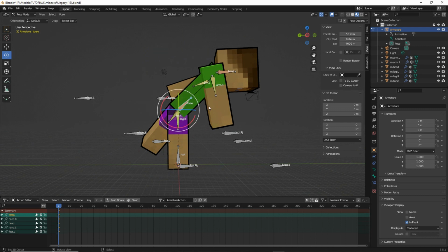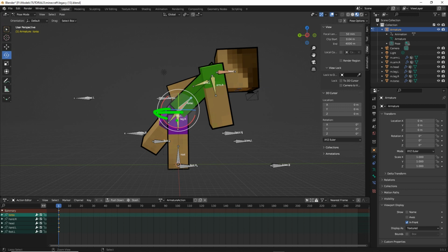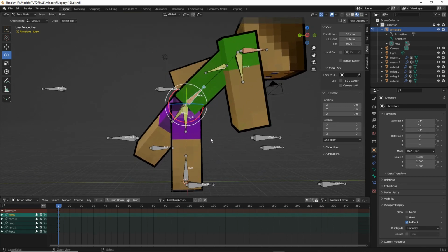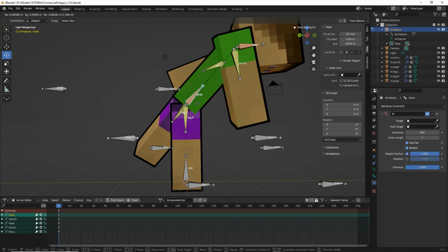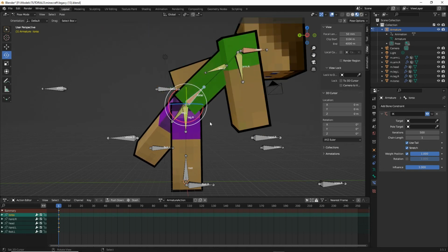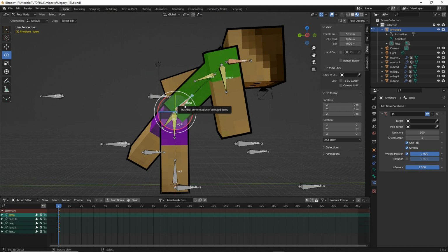So if we want to move this bone backwards a little bit, but currently the IK that we set up there doesn't permit that. It only rotates that bone. And this is why we do a simple pose to double check. So we go back into bone constraints. We need to double check the manipulation or the articulation of the bones before we do any complex animations or complex poses. So we can do one of two things here.